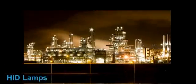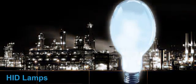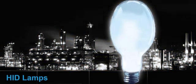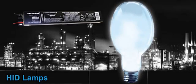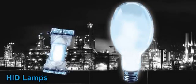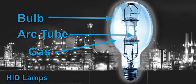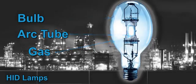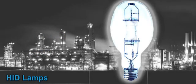Next, we'll cover high-intensity discharge lamps, also called HIDs. Like fluorescents, HIDs also feature electrodes and require a ballast to step up the voltage to maintain operation. In an HID, the electrodes are inside an arc tube within a bulb. The tube is filled with gas and with metals. The gas helps start the lamp. However, when the metals are heated to the point of evaporation, light is produced. Because an HID lamp takes anywhere from 3 to 15 minutes to achieve full brightness, they're not used for applications where lights are frequently turned off or on.